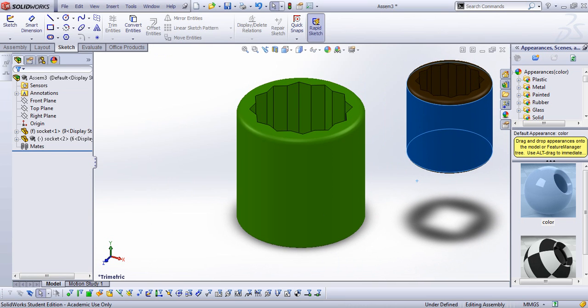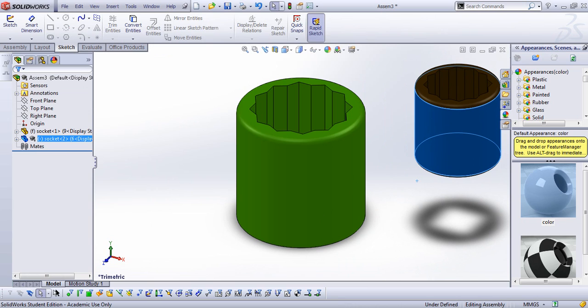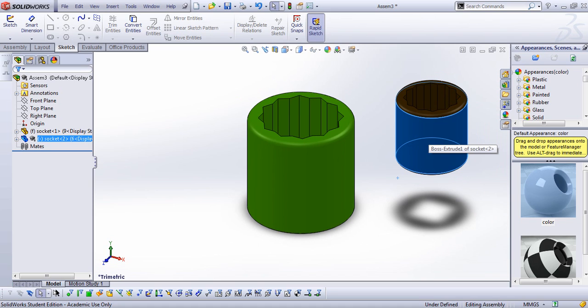And this is how easily you can make one drawing in one part, and then generate as many parts as you want using this design table. It was a little different in the previous version, and you had to do it a little more complex. You give it global variables and do the relations, but in this newer version, 2012-2013, it makes it actually easier.